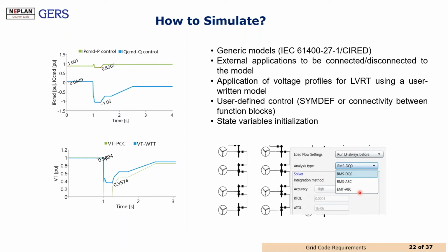Another requirement is to define a new kind of disturbance of the power system. Before, we were able to validate the system performance during a specific short circuit, or the system performance if any contingency occurs. But today, speaking about fault ride through, a new kind of disturbance has to be defined. That definition is called the low voltage ride through event that we are going to check later. And the software should be able to provide a tool to create this kind of event.